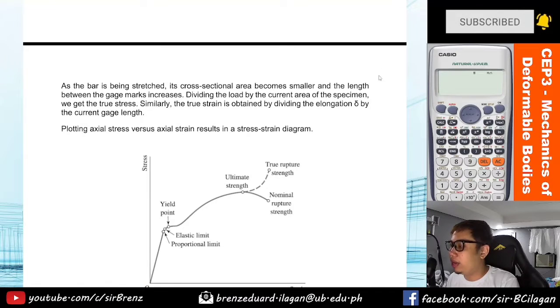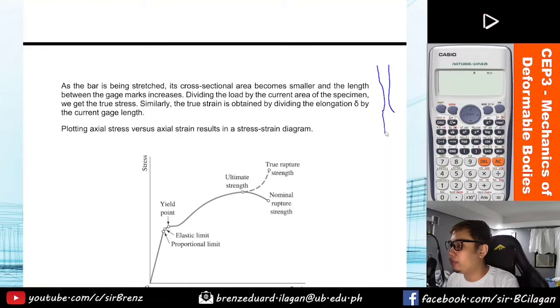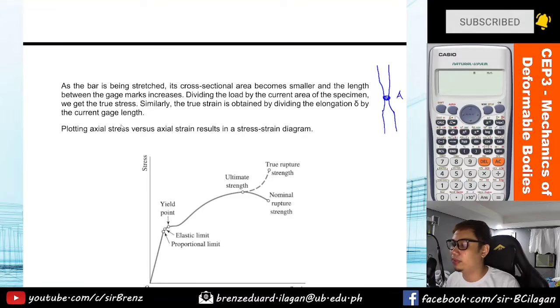So, habang ina-apply mo yung force, kung mapapansin nyo kasi, nagkaroon siya ng necking na tinatawag, or yung area niya ay unti-unting lumiliit sa gitna. Ayan. And again, yung area na yan yung gagamitin mo din ulit dun sa formula for the stress. Dividing the load by the current area of the specimen, we get the true stress. Okay? So, yun pala yung true stress.